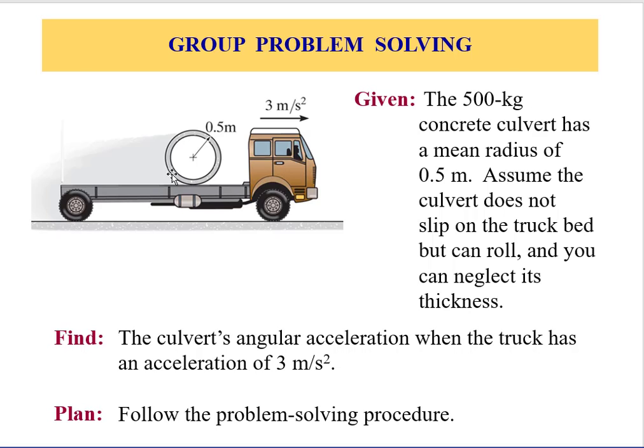First, drawing the free body diagram, labeling the forces, examining this point A, and then applying the kinematic equation, right, with the contact acceleration of 3 meters per second squared, so that we can relate aG, because the three equations that we'll obtain will have 4 unknowns, and we need another equation which comes from kinetics, which links it to the 3 meters per second squared.